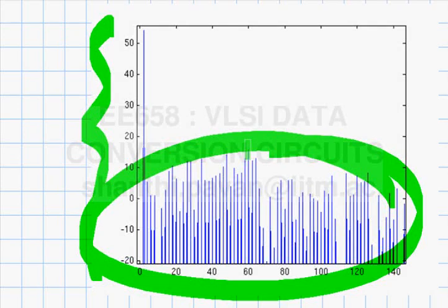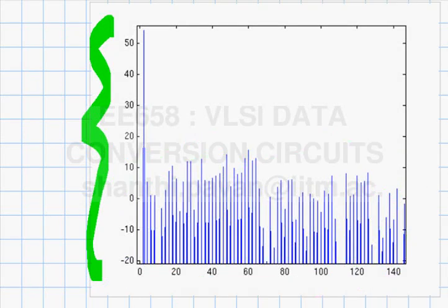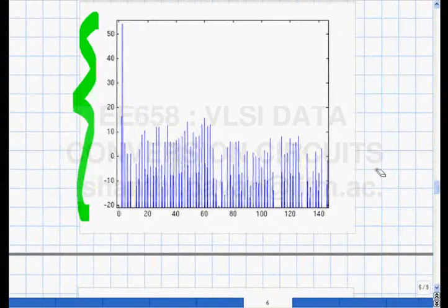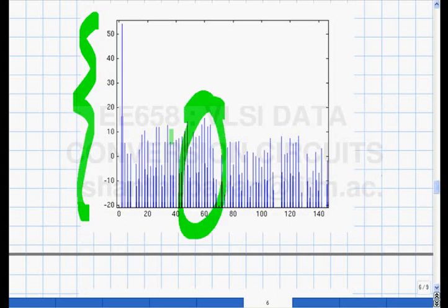the quantization error sequence. This looks quite garbled, and many would wonder if there is any intuition at all to be gained from a plot like this. It turns out that there is, and the intuition here is to notice where the peaks are occurring. If you look at the maximum peak in this picture, around which harmonic is it occurring? Around here, right? Around 60 odd. Between 50 and 60, there seems to be a distribution.